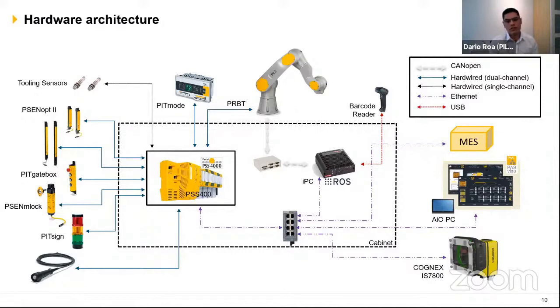One of the caveats of ROS is that it's not handling safeties just yet. So to solve this and to be able to properly bring the machine up to standard, we use our safety controller. This architecture allows us to have more freedom in the ROS part on the one hand, and second, not worry about the safety for now inside ROS.